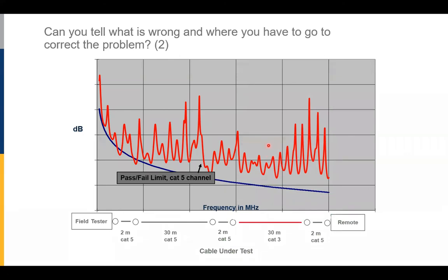So again, when we're looking at a test result, and here's a near-end crosstalk problem, we have the strength on the vertical scale in decibels versus the frequency where it's operating. The standard requires us to report the measured interference in the frequency domain. So this link that was built, first of all, we see this failed. See that measured value is below the limit line.